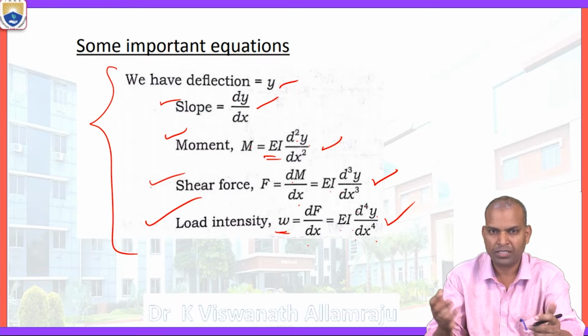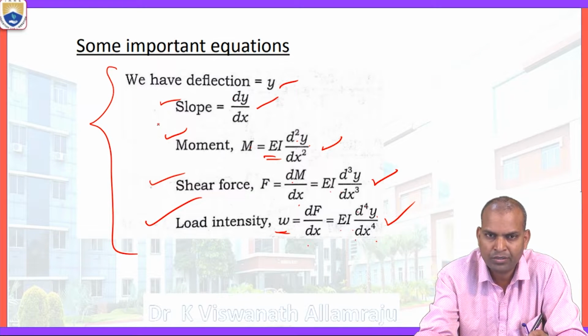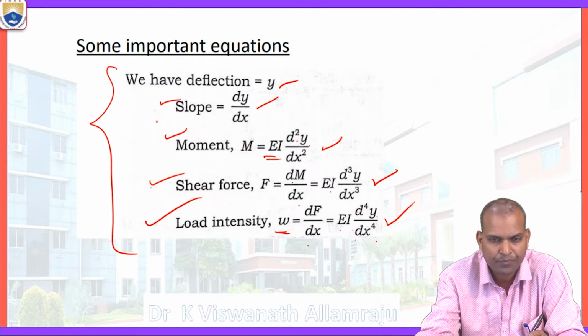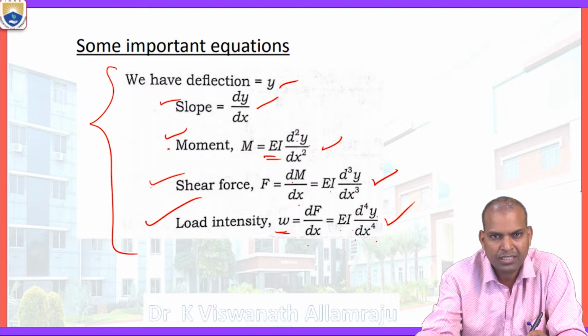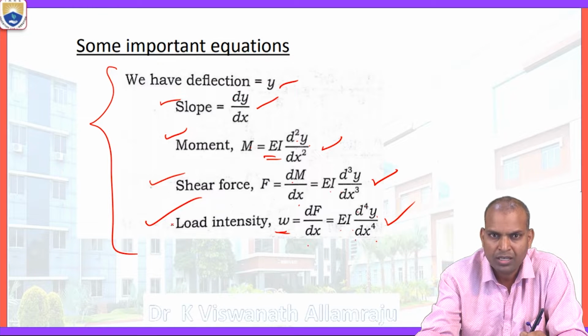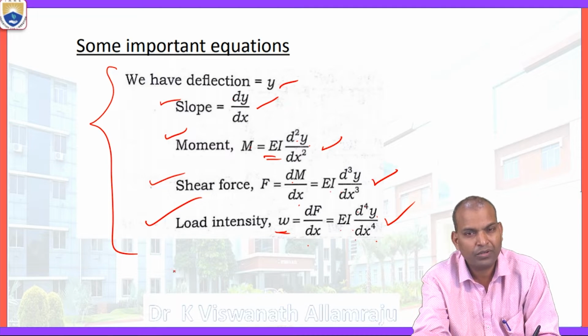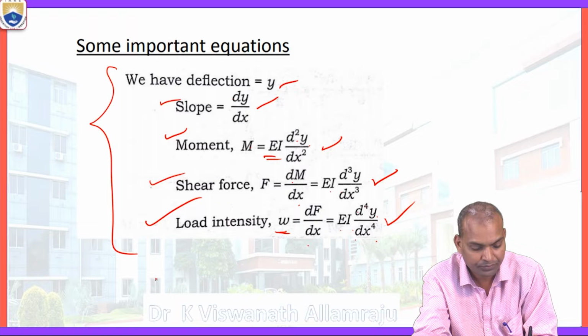If you know the deflection, from that the slope can be calculated. If you know the slope and the modulus of elasticity and second moment of area, the moment can be calculated. Differentiating the moment gives the shear force, and differentiating the shear force equation gives the intensity of the loading, so how much load is being applied, from the value of the deflection.